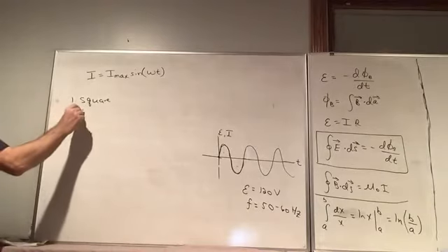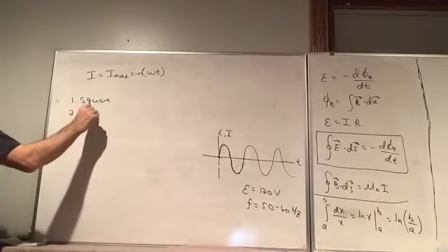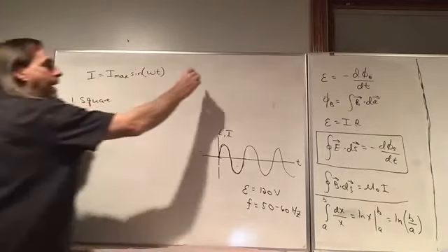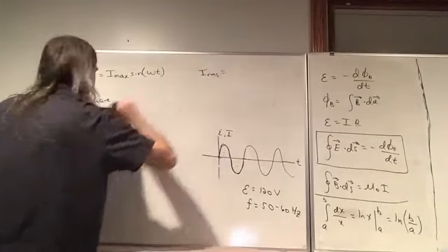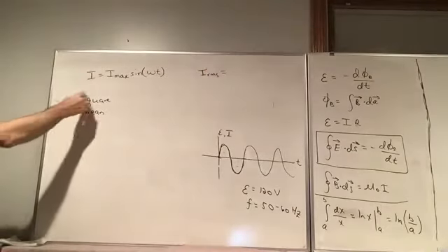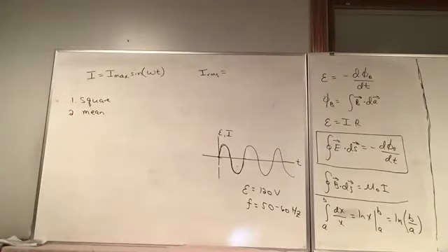And now we can take the average or the mean. I'm calling it mean because remember IRMS, the M stands for mean. So once we square it, we have all positive values. Then we can average the result. And the problem is that once we square it, we're dealing with amps squared now.